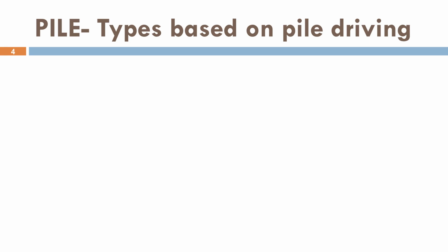The selection of a suitable installation method depends on several factors, including soil type, groundwater level, pile dimensions, noise restrictions, and nearby structures. In urban areas where vibration must be minimized, bored piling is generally preferred. On the other hand, driven piles are suitable where dense soils require displacement for improved bearing capacity. Precast concrete piles are further classified as RCC piles of full length, jointed RCC piles, and hollow tubular section piles. Also, preformed steel pile is classified into H-section, box section, and tubular section piles.